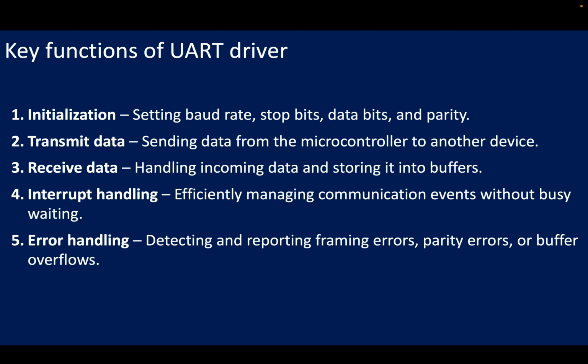So what are the key functions of a UART driver? This is where the software programmer actually develops the code for the UART device. Mainly the first one, initialization. The driver has to set the baud rate, stop bits, data bits, and the parity. Then the driver must have the implementation to transmit data, sending data from the microcontroller to another device. Then it will have receive data functionality, handling incoming data and storing it into a buffer. Then one of the main important portions of the driver is interrupt handling. Then error handling, detecting and reporting frame errors, parity errors, or buffer overflows.